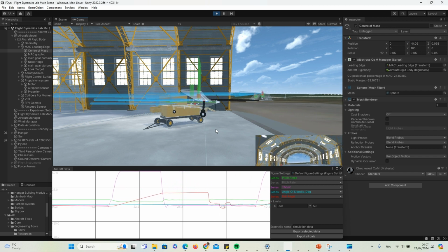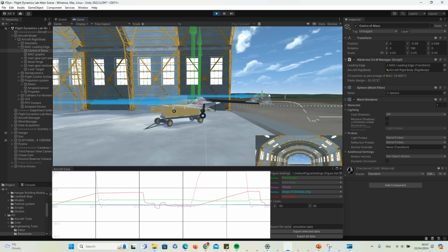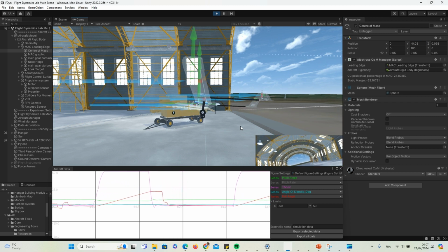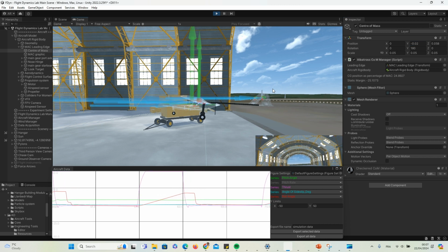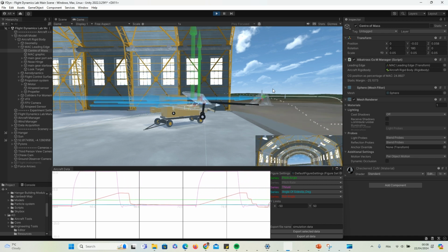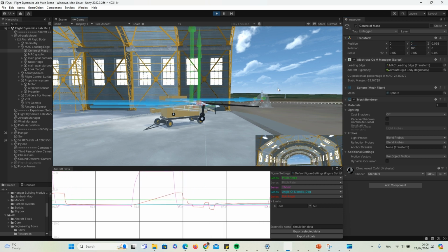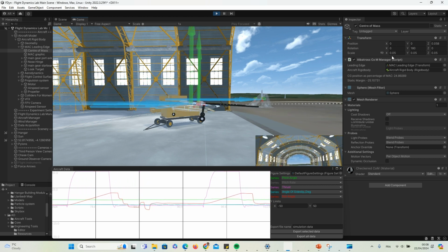However, as we start to reduce the vertical position of the center of mass, we notice that the pitching response is reduced, and once we achieve a value of about minus 0.03 to minus 0.02, the pitching response of the aircraft is almost zero, and thus placing the center of mass in this region will provide the pilot with added stability and no issues from varying the thrust in flight, so the trim would be maintained for much longer without needing to retrim after every thrust change.